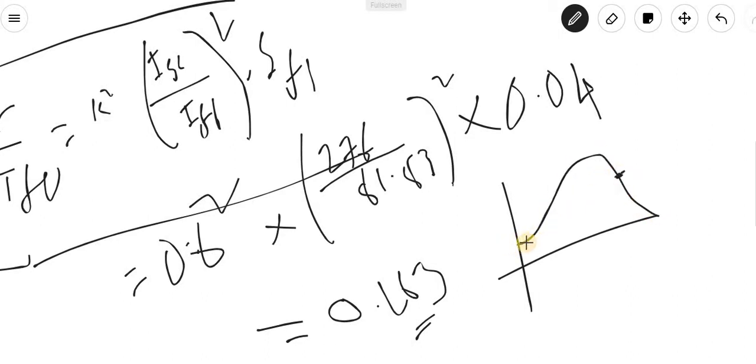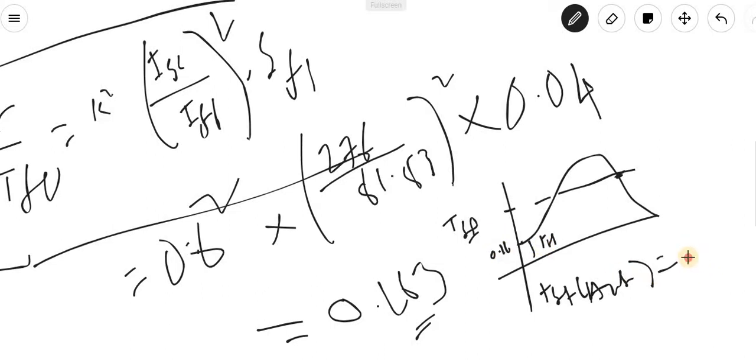So that means it is like this. Suppose it is full load torque, with the starting torque 0.6. Starting torque in case of auto transformer is the 0.6. But when it is full load torque, we know that it will be run directly to the supply. There will be no auto transformer, so it will be running condition.